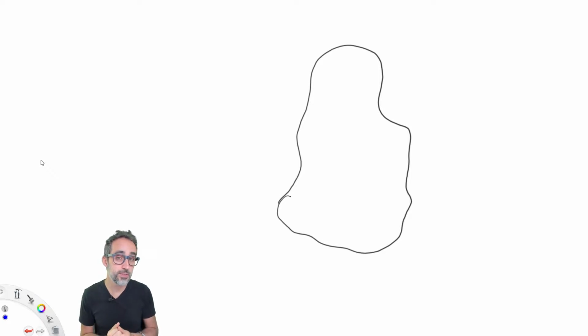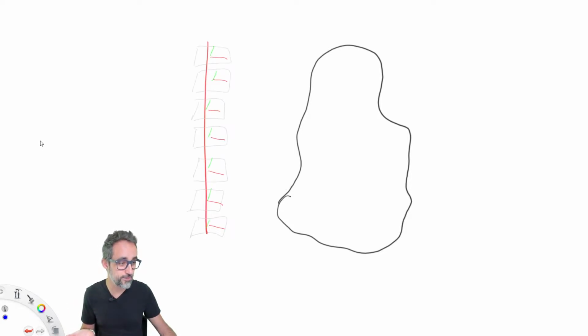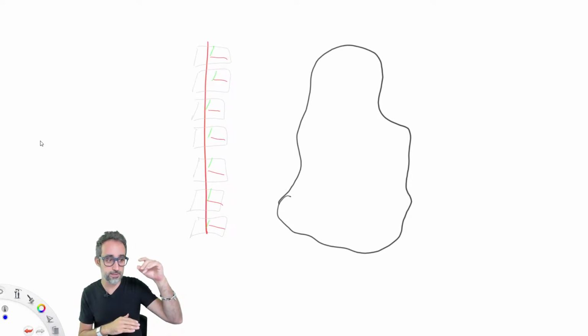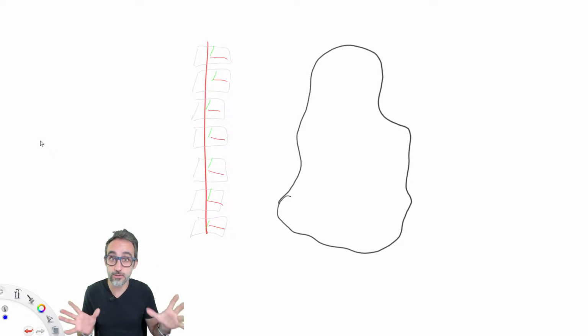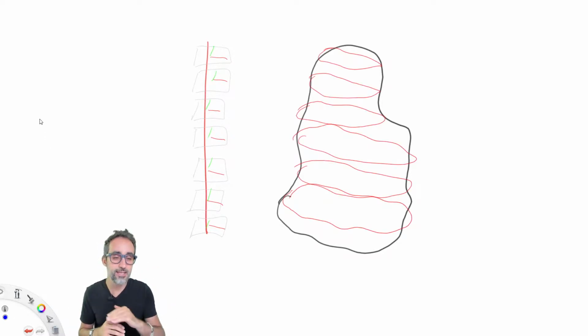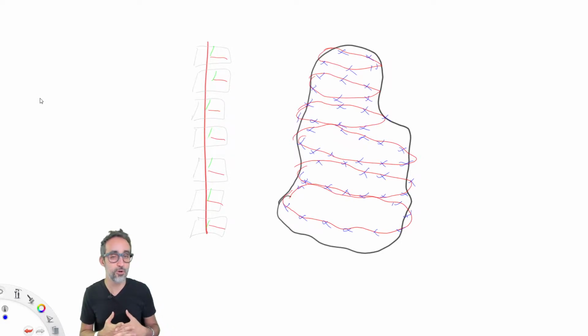The first thing we need to do is turn it into a mesh. And this is very important because no slicer that I know of in the world works with NURBS geometry. Internally, they always end up translating it into meshes. The process of slicing involves creating a set of planes that are spaced a particular distance between them, then intersecting the object with those planes and then subdividing each one of those contours into individual points.